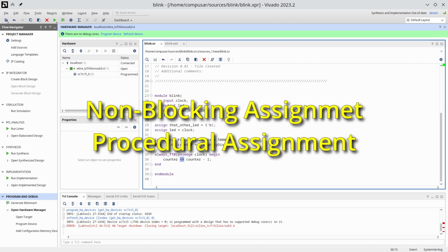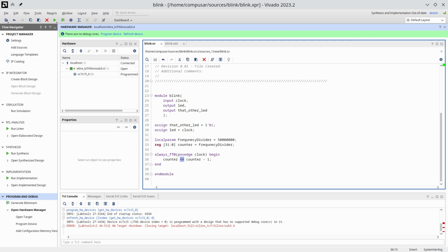When running in a simulator, pay attention to visibility. Blocking assignments immediately show up in the variable's value. Non-blocking assignments only take effect after the clock edge. That is actually the reasoning behind the naming. With that said, I advise you not to overly rely on that effect, lest you end up with code that works only in the simulation, not on a real device. If you don't know what any of that means, don't worry, we'll get to simulation in some future video.